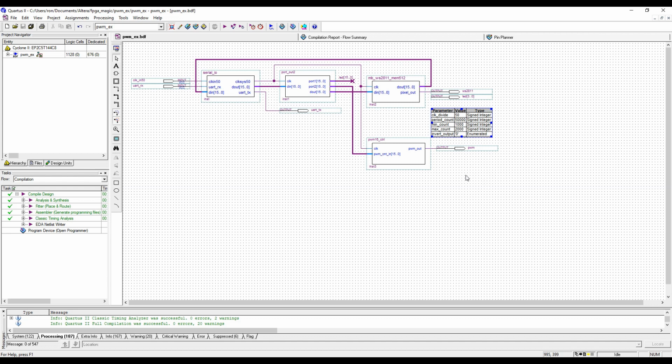The servo position is usually bound with a pulse width between 1 and 2 milliseconds, so our min and max count are bounded at 1000 and 2000, which bounds that output if the input from the control software is set other than in between that. If you don't use these, you can set the min at 0 and the max count at max, which is 65,000. You can see the documentation on the macro for more information. In addition, there's an invert to invert the output.